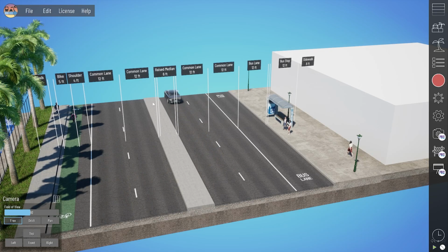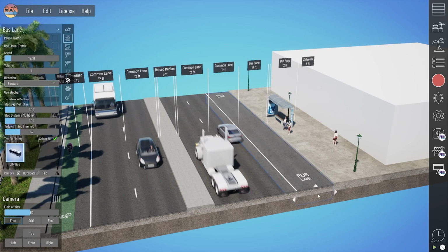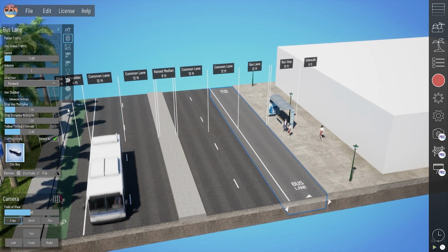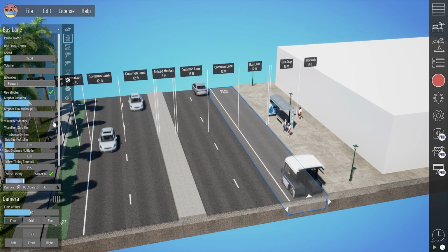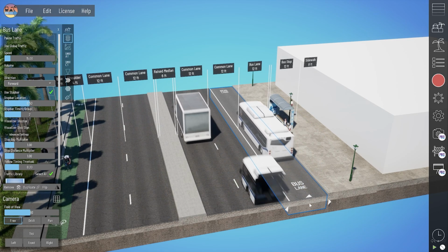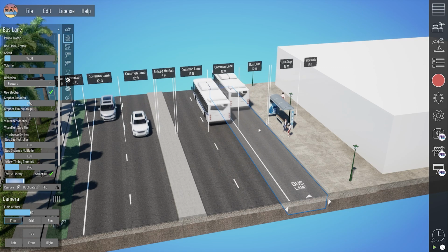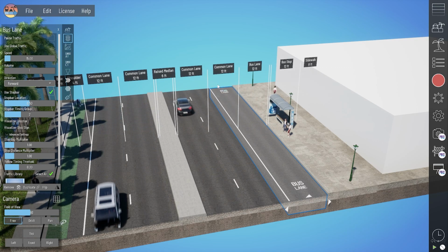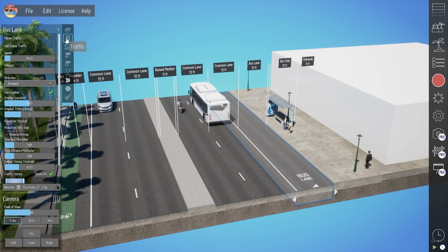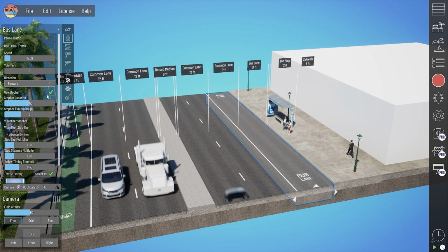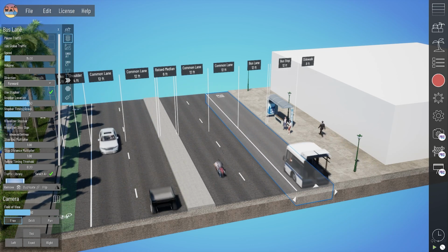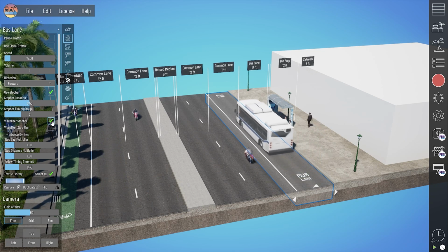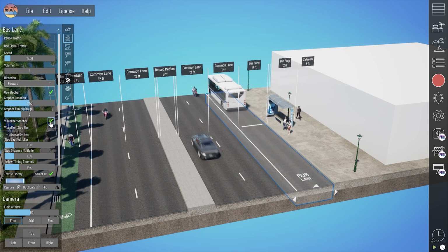We have some advanced traffic settings new to Beyond Typicals 2, particularly in version 2.1. We are able to add in a stop bar to our section. What that will do is show traffic temporarily coming to a stop and then accelerating through your section. In our traffic menu, in our section dialog box, we have a toggle to use a stop bar. We also can turn a visualizer for that stop bar on to see where it is in the section.